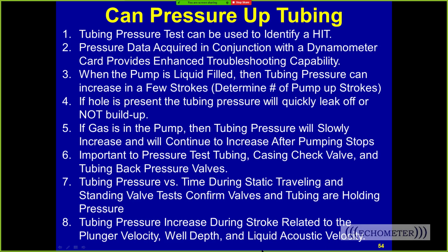This last sentence is something that I toss in here because sometimes people talk about when the tubing pressure's up during a stroke. And one of the things I wanted to show, and I showed it a little bit, is that the pressure change in the well is a function of the acoustic velocity of the liquid. So water has acoustic velocity about 4,300 feet per second, in that range.